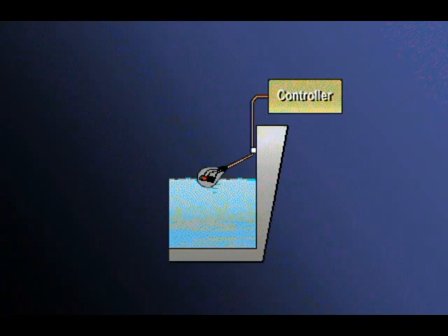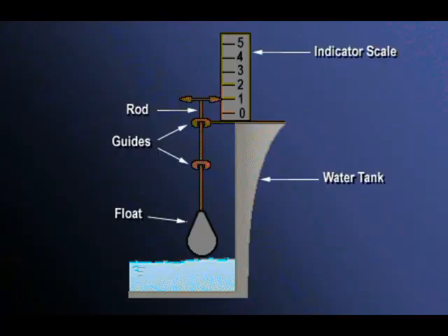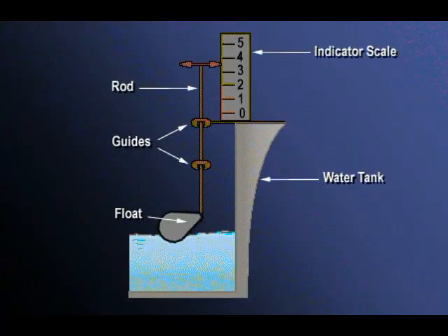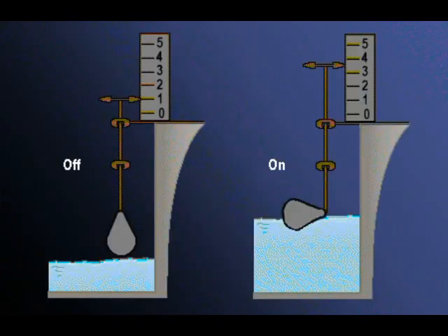Level sensor control devices are usually pear-shaped floats, like the one shown here. It is a simple and rugged device. If the water level is low, the float switch hangs vertically. When the liquid level rises, the bottom of the float tilts. The movements of the float switch from vertical to tilted positions open and close a switch inside the float. This controls the pump motor by turning it on or off.